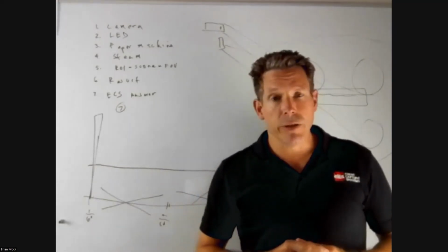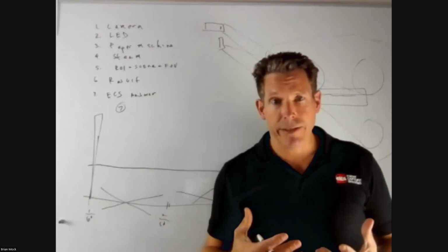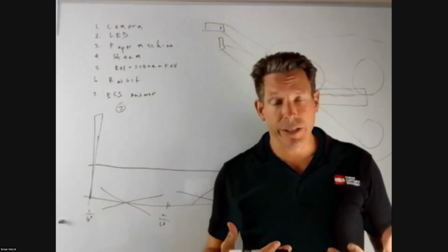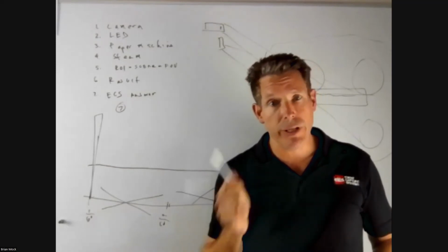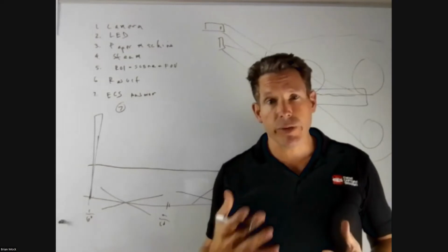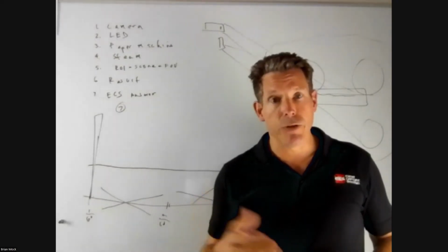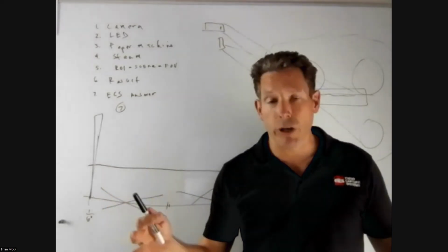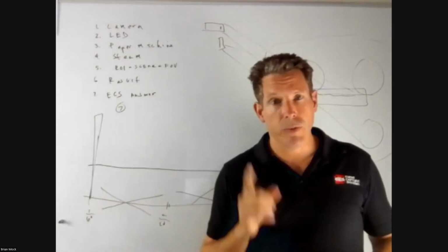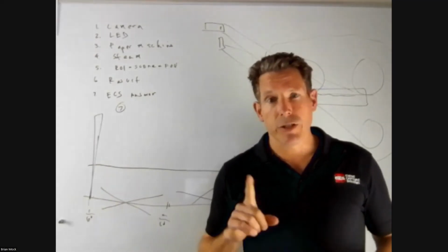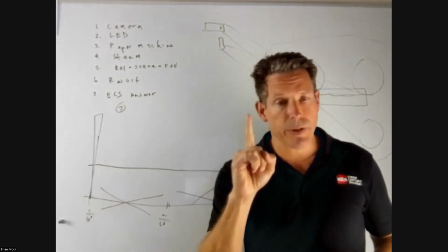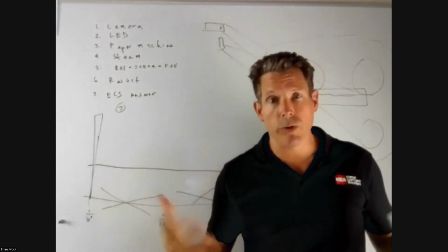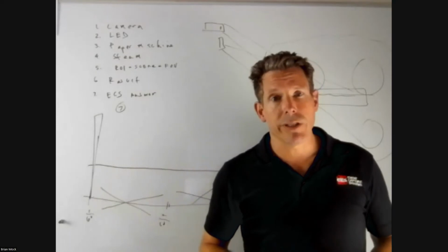The other problem that you get into if you don't have the right light, and we talked about this before: what do cameras do when they operate in poor conditions, when they are light starved? I'll show you the examples, but to talk about it here, three distinct things happen when you don't have enough light. You can still produce an image. You can have a 3 million pixel image of nothing but blur because the light is not there. Number one, there's no contrast because you have to bump up the gain, which is an artificial aspect of what you do. Signal to noise ratio then suffers because you have more noise than you have signal. So the image quality goes down significantly.